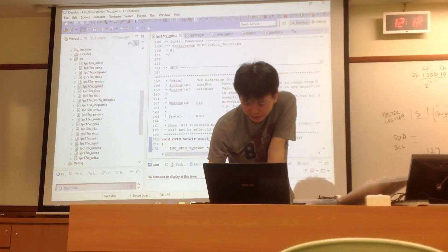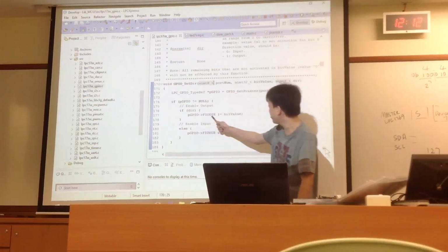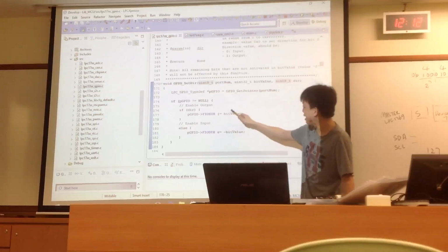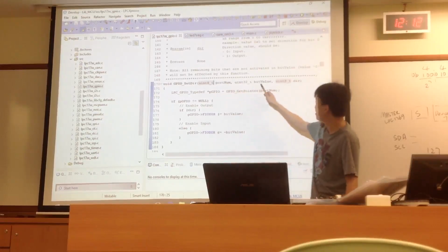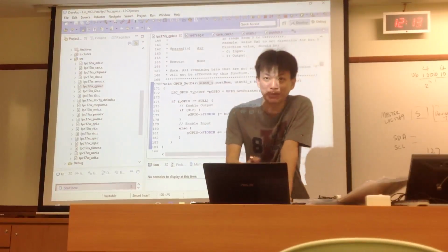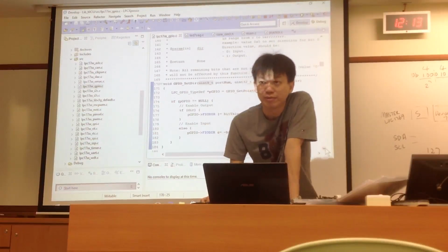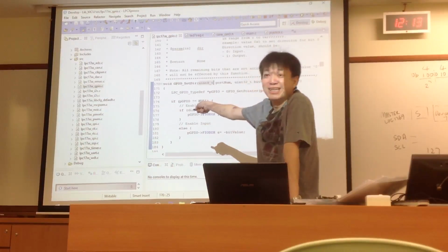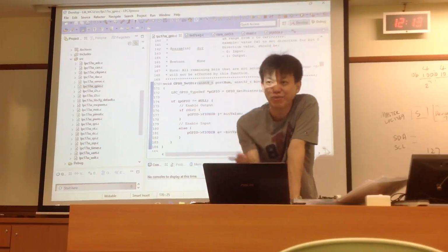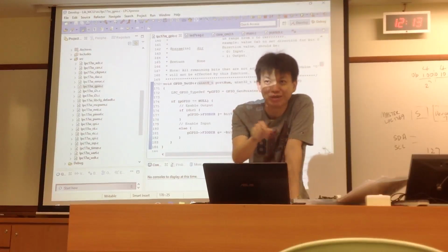If you want to set the direction, you don't need to know the address of FIO direction. They will get the address for you and update the value. You just give the port, give the value, then tell it the direction. That's how we set all the interfaces, GPIO. It's because we have this MCU library. Otherwise, you really need to understand whatever you learned in lecture 7 and lecture 8, and then write in assembly yourself and so on and so forth.